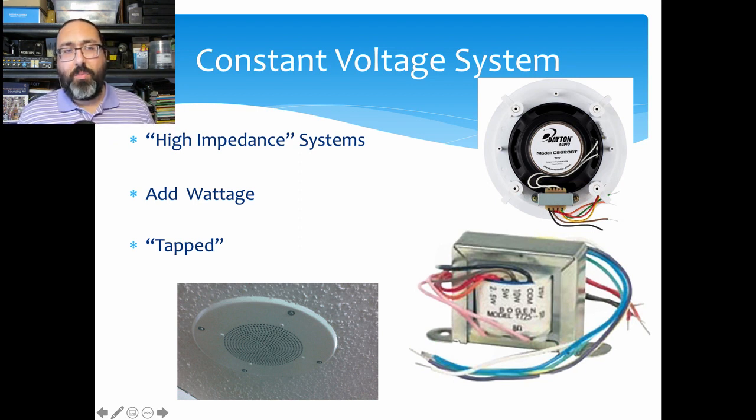This kind of works the same sort of way, in that you would have a bunch of speakers. And the nice part about that is you can wire them in any way you wish. Series, parallel, it doesn't really matter because you are tapping into a powered system is how it looks at it. And then from there, all you're doing is adding that wattage. And as long as you leave at least 80% for safety, so if you have a 100-watt system, as long as your wattages only add up to 80 watts, then that's considered safe and considered good.